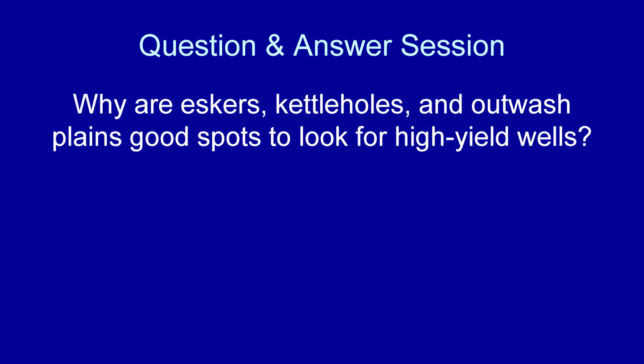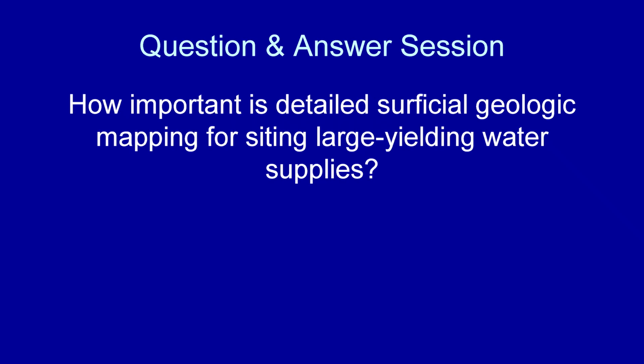Great, thanks. And we've got one other one. How important is detailed superficial geologic mapping for siting large yielding water supplies? Superficial mapping is going to be beneficial because it is going to help you in several ways. Number one, it's going to show you what the potential for the underlying saturated sediments will be, but also you should be able on that mapping to look up gradient to make a determination how much watershed is up gradient to provide recharge.